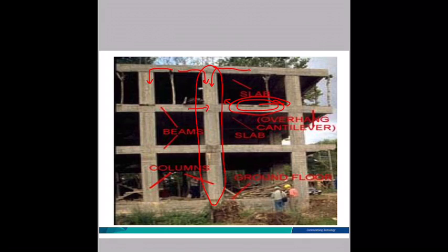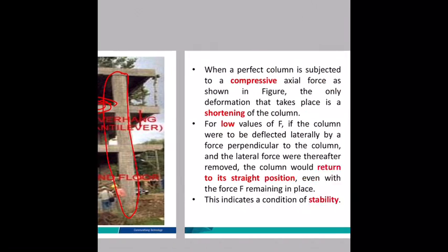The slab load is also transferred to this column, and all the load transferred to the column will be transferred to the foundation. And at the foundation you also need equilibrium for the column and the foundation. Inside here you will have a soil bearing pressure. That's why I mentioned column here is the main structure of your building.